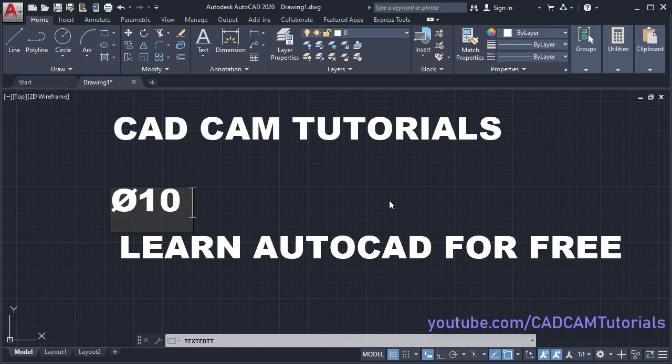Suppose I want to write degree, suppose 45 degree. Again you will have to type %%D. Then that will get converted into degree symbol. Same way, suppose if you want to use combined plus and minus sign, then you will have to type %%P. Then it will get plus minus. And if you want to underline some text, then take your cursor before that text and type %%U. So that text will get underlined.